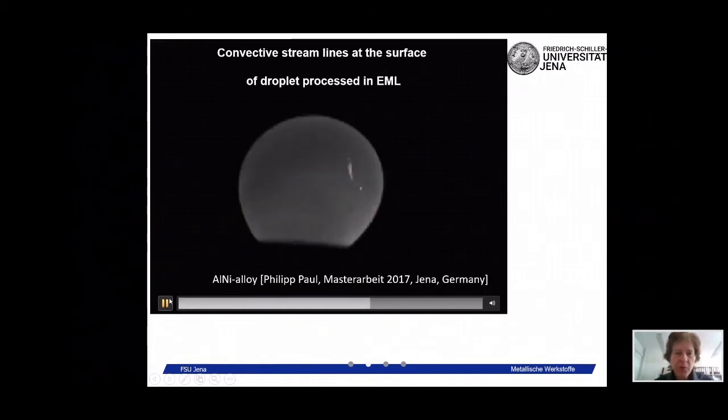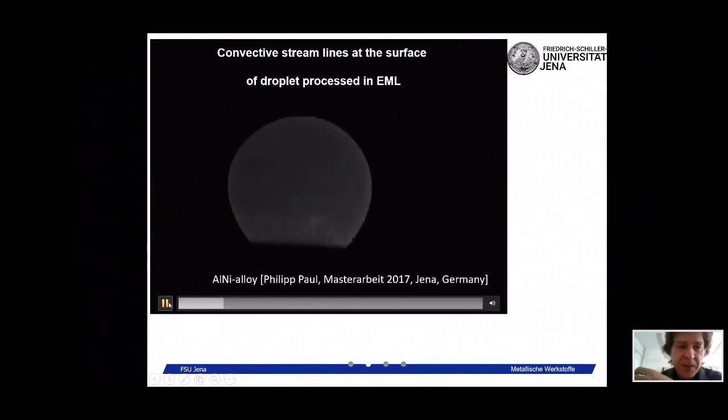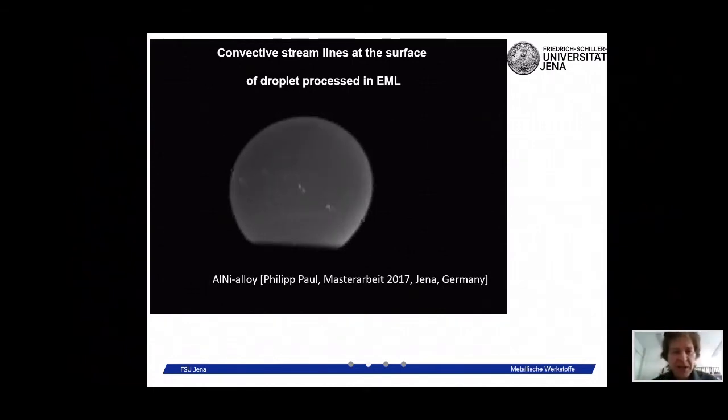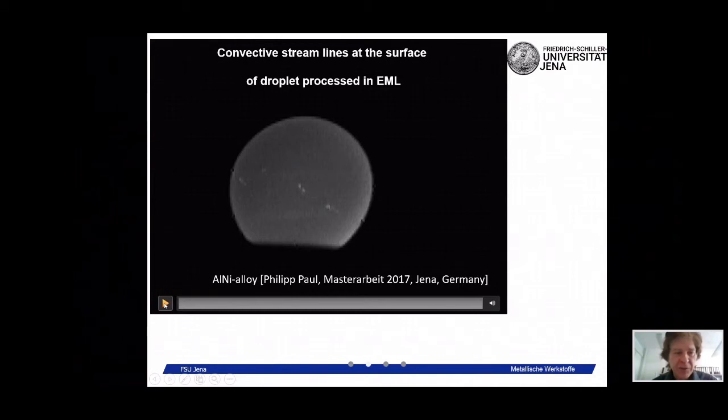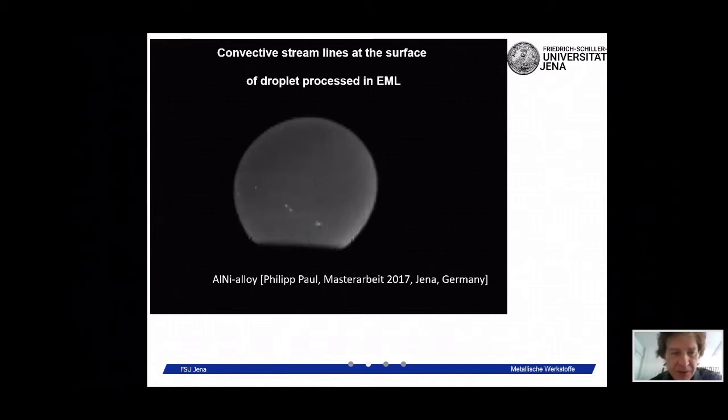Stop. So that's it. We have made measurements of this interface velocity as a velocity of dendritic tips once again. And then we can say that the primary solidification begins and stops during some time for a given undercooling. So this is a typical measurement, a typical propagating front of recalescence in our case.